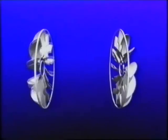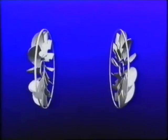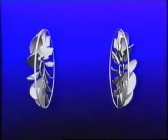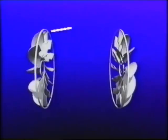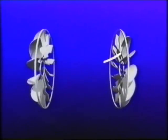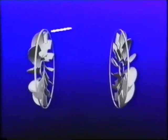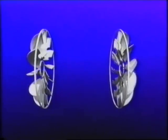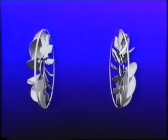As we saw in the experiment earlier, the fluid coming out of the pump impeller hits the blades of the turbine runner, and this causes the turbine runner to begin rotating. Now, what happens when the fluid returns to the pump impeller from the turbine runner? Uh-oh, the fluid is hitting the pump impeller from the wrong direction, isn't it? Won't this interfere with the rotation of the impeller and reduce torque rather than amplify it?